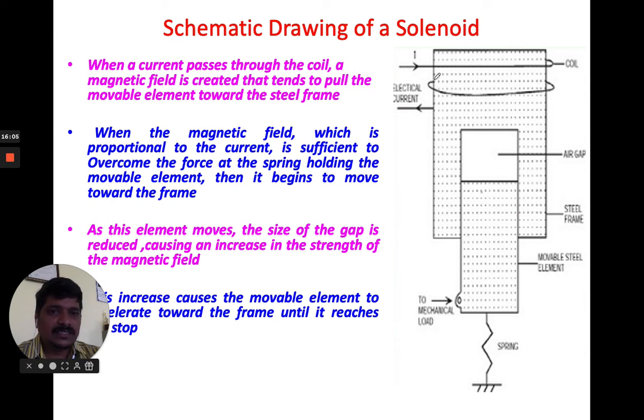Whenever the coil is energized, it tries to pull downwards. At that time, whatever fuel pressure is there will go into the engine system. So this is how the concept of the fuel injector works in a vehicular system.